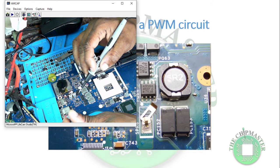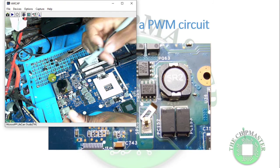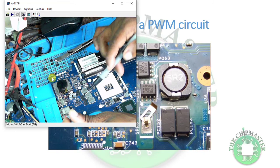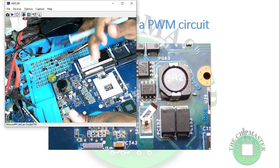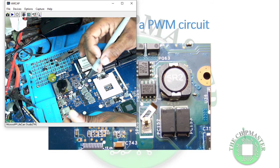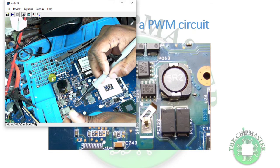So the PWM circuit of the CPU power supply is very complex, right? This is a class by itself, right? So it is a shared current, so each should give at least 45 ampere, and it's connected in parallel to produce 90 ampere, right? If you go over 90 ampere, then it is over current protection. The chip has a VR hot pin.